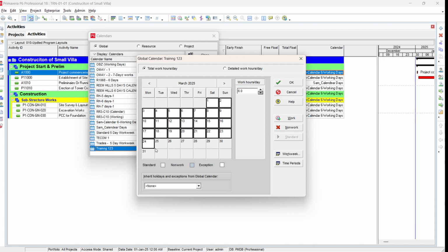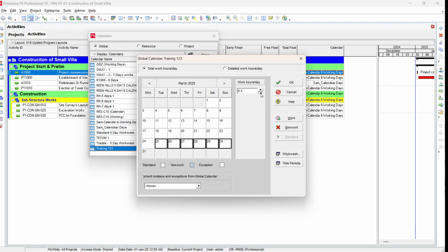Then you have this 30. Sorry, you have to select from here. This also you have to select, press shift, and then reduce to 6 hours. And 31st is a holiday in the Gulf countries, so make it non-working days. In this way you can put any days you want. For example, 1st May is a holiday, so make it non-working days. And consider 18 to 21 as holidays in Gulf countries, so non-work days. Similarly, you can assign holidays of as many durations as you want.